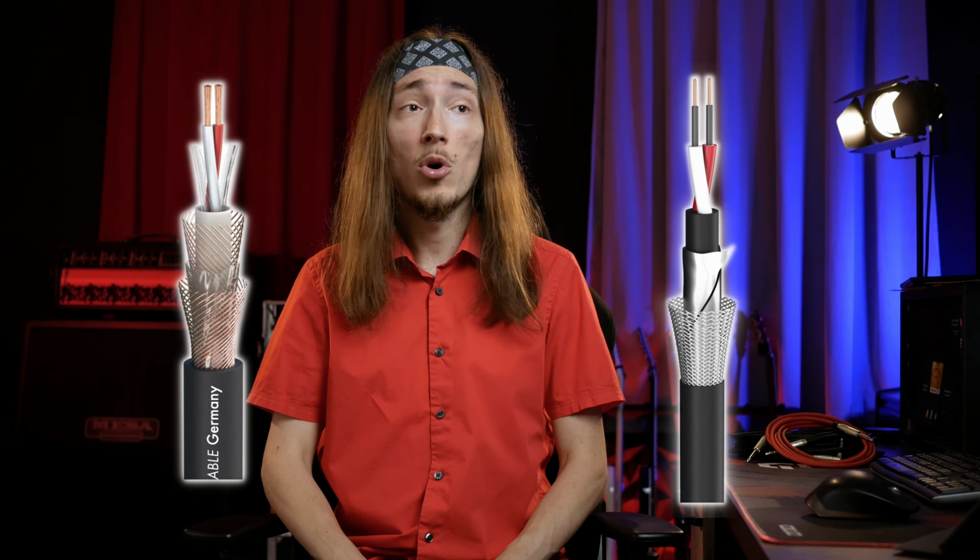Fifth, shielding. Sonically, there is no difference at all. If you are doing some permanent installation, or if you want to use some expensive cable for your expensive U87, then yes, you can stick with some double layer or some more advanced shielding, but keep in mind this will only make your Faraday cage stronger, but only in the electric part of the noise. The magnetic part is still in